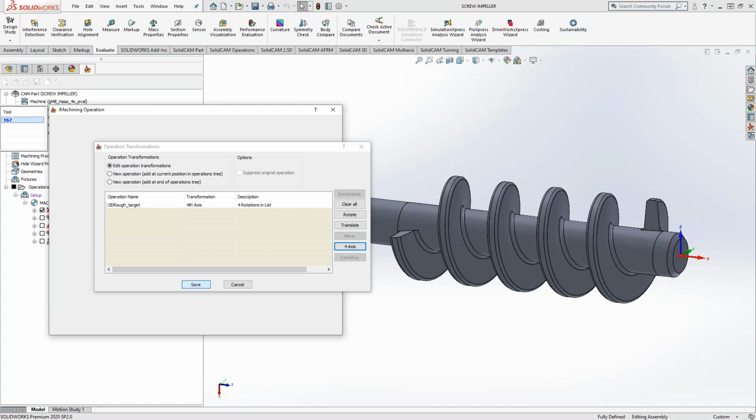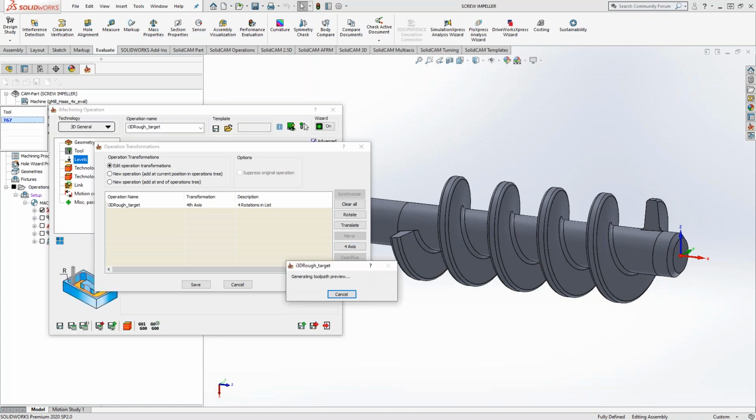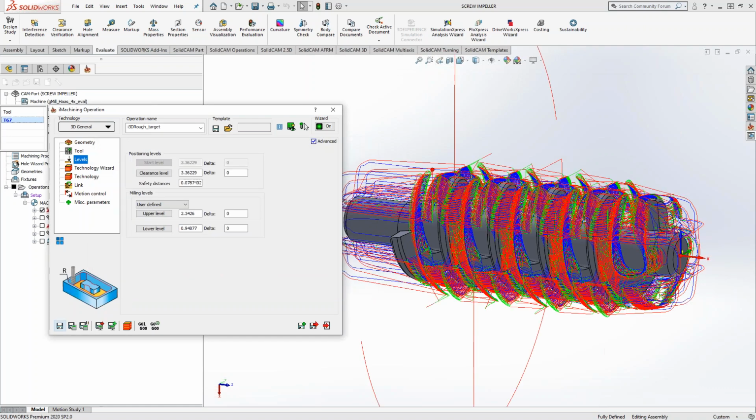But what that's going to do is it's going to take a renewed look at the stock at those 90-degree positions. So this is kind of like what Kevin was referring to before, and yesterday, this is what Brad was asking about. If you have 3D iMachining, you can actually get it to rough this out like this, and then go in there later with your simultaneous toolpaths or your Swarf toolpaths and get it to clean up those spaces. And if you're looking for a reduction of cycle time, this versus the wrapped versus the simultaneous toolpaths usually is a little faster.